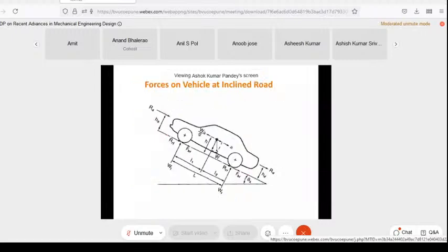After that, the forces, right? Important forces you have here: the force through which the trolley is connected, right? Then you have here air drag force. This is your aerodynamic force, air drag effect, which is acting at, let us say, a distance h from this. And of course, it will depend on the centroid of this frontal area, right? This is your frontal area, isn't it? The wind will also be acting at the CG centroid of this frontal area, which will be offset from the actual CG of your body.